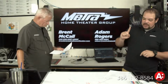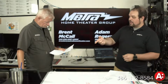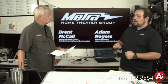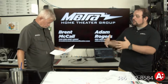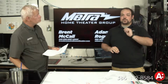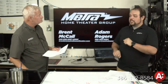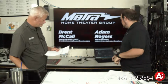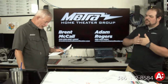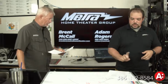On the 802.3 AF standard, the PD requires at least 12.95 watts at the powered device. The nice thing about this standard is that it allows manufacturers to say, okay, I can operate at 12.95 watts, because they know they're going to have that much power at that side. That doesn't mean we have only 12.95 watts coming out of the PSE, the power supplying equipment. That can increase because of distance, all the way up to 15.4 watts. So there's a lot of headroom, and it increases as you go up, not exponentially, but possibly substantially in some cases.